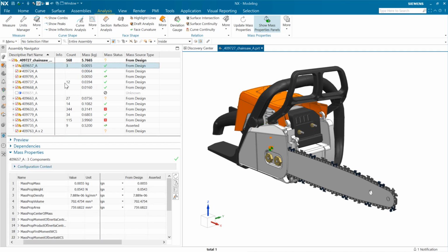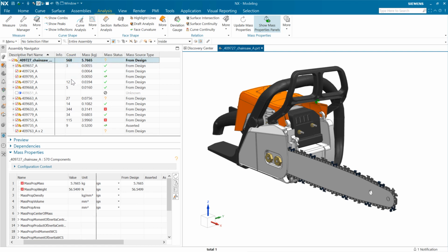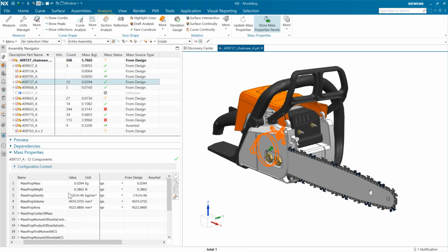If we're selecting assemblies as well, we're getting those assemblies. Here's that one with the center of mass marker in the middle. Really all of these, of course, you're seeing that center of mass marker, right? And similarly for the top level assembly, we can do that as well. With these, again, the values below are going to be the aggregated properties of the parts that are there. And with these, we can choose which source we want to use for these numbers.